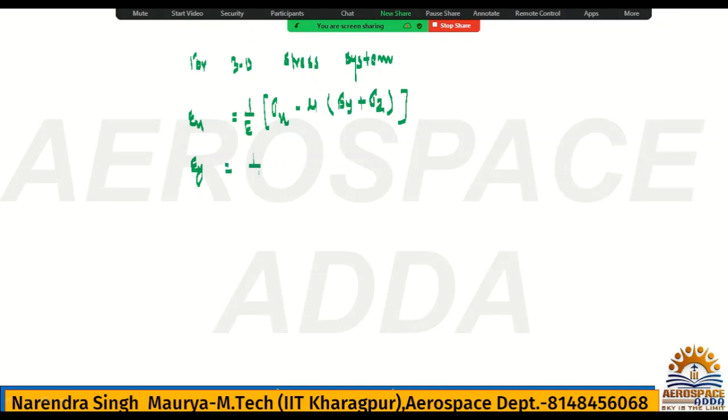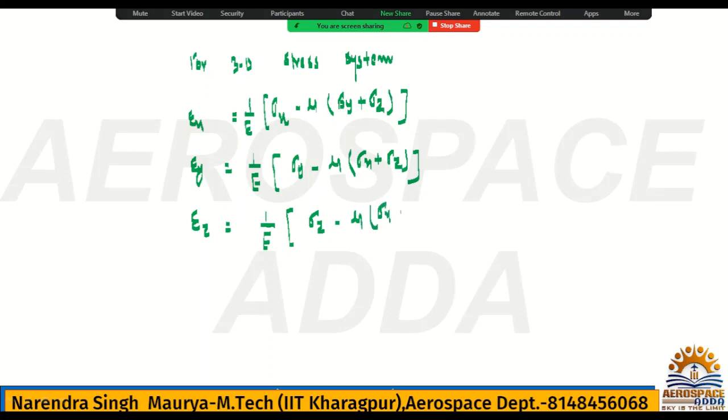Epsilon y is 1 upon E in bracket sigma y minus mu sigma x plus sigma z. Epsilon z is 1 upon E in bracket sigma z minus mu sigma x plus sigma y. So this is all about strain.